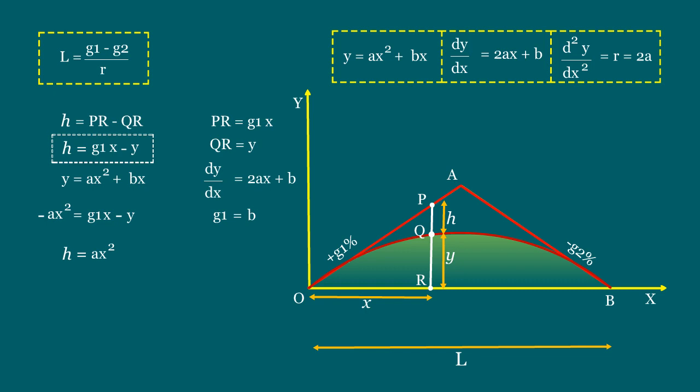Here, a is a constant. In vertical curves design, this constant is denoted as k, so we can call this as h equals kx square. X is the horizontal distance in algebraic formulas. So, x can be replaced as n, because n is the total number of chords with uniform intervals, counted from point O, which covers the total length of curve L. Finally, this can be marked as h equals kn square.